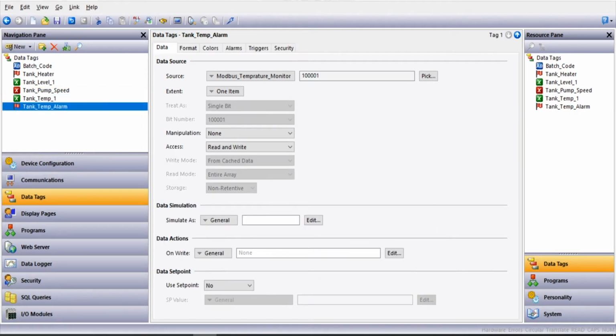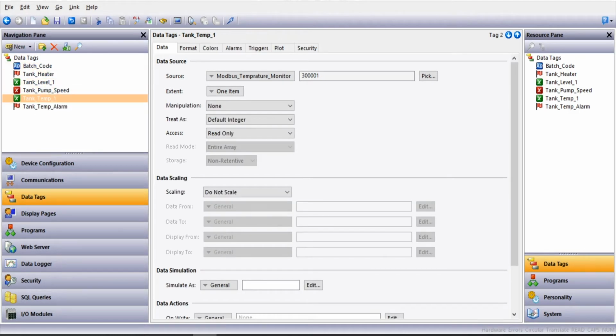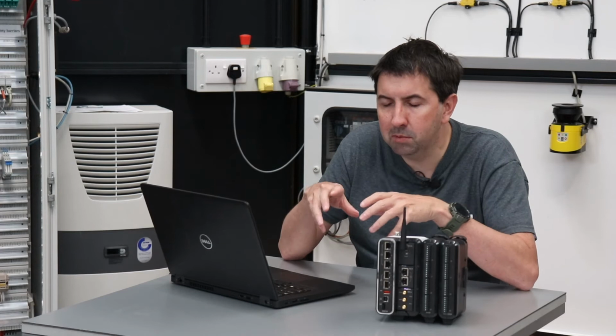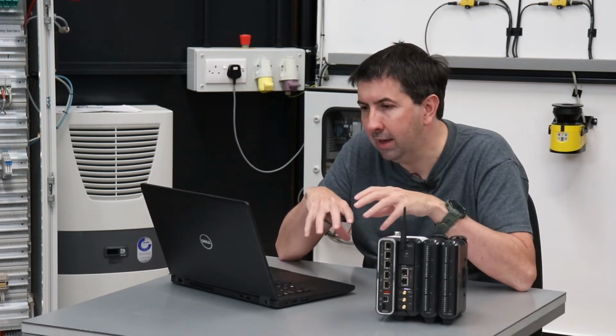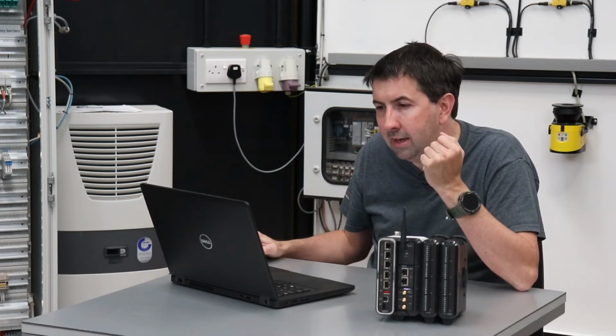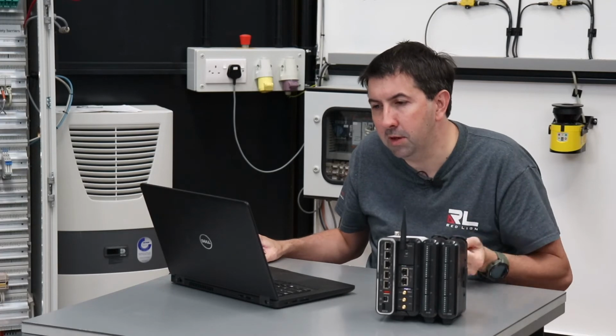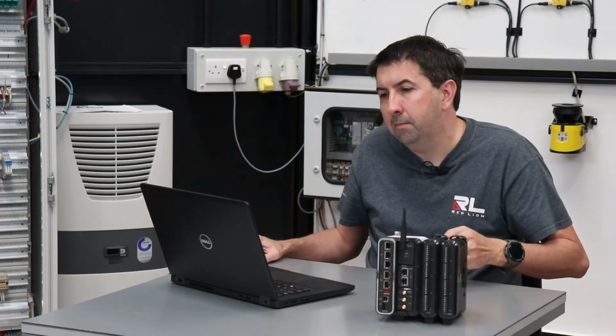In addition, what I want to do is monitor this tank alarm, and if that tank alarm goes off, I want to capture everything that we have about this tank as a one-off triggered snapshot. So we're taking two types of data log here. We're taking one every 60 seconds and another one when an alarm goes off. So this is how we do it.